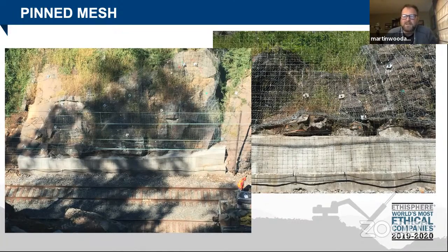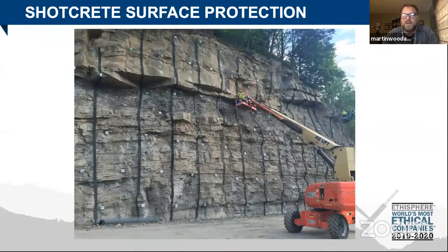But what happens if you're going to have a slope that's really, really prone to weathering, differential weathering, and changes dramatically over a short period of time? This is very common in a lot of the coal-bearing regions. So in these regions, you have durable units, like sandstones and limestones. You have less durable units, these are shales and coals and claystones and those types of units. And what happens is very quickly, the shales weather away and leave these large overhangs.